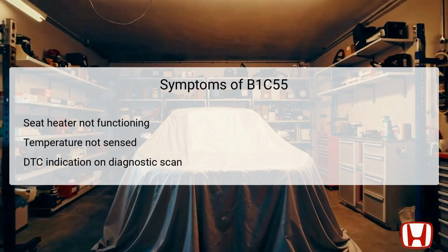The main symptom of the DTC B1C55 is that the driver's seat heater does not operate, leaving the seat cold when heating is expected. As the thermistor is integral in monitoring the seat core temperature, any failures may lead to the system being unaware of the current conditions, thereby failing to turn on the heater.